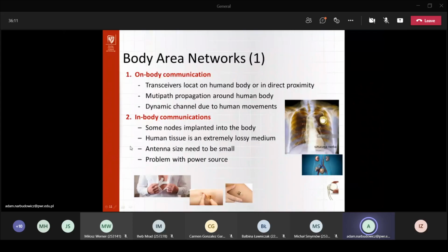Well, the main challenge here is that humans are basically pretty much bags of water, right? So 60% of our body is water, which is basically a dielectric that is lossy. So it attenuates the electromagnetic energy quite strongly. And that is a challenge, of course, because, I keep repeating, in free space propagation you have attenuation to the power 2, which is already quite bad, right?